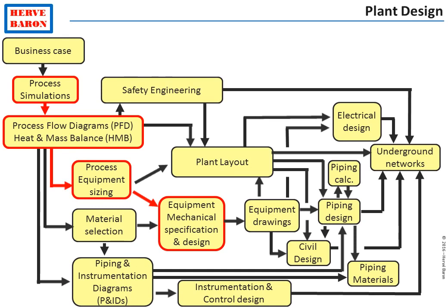Therefore, the equipment must be ordered at an early stage in order to have the equipment vendor information early to develop the plant design. So, the first critical path is that leading to ordering the process equipment.